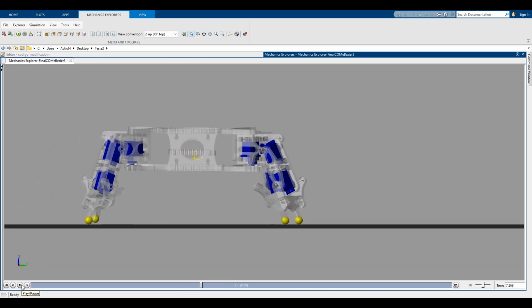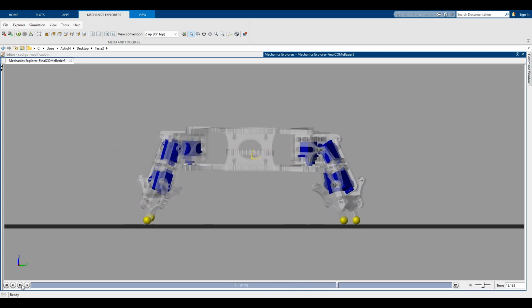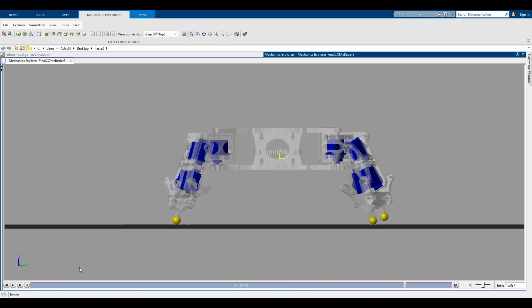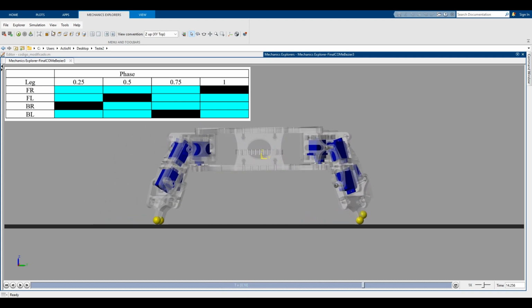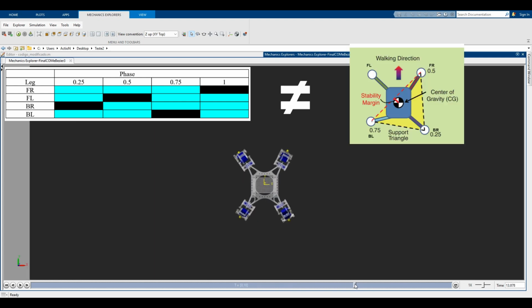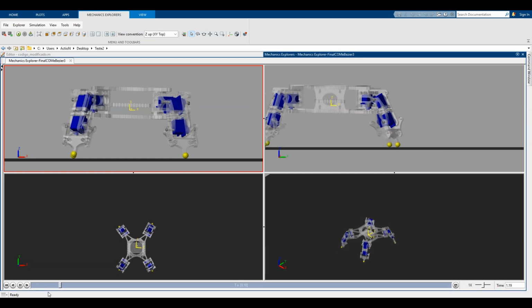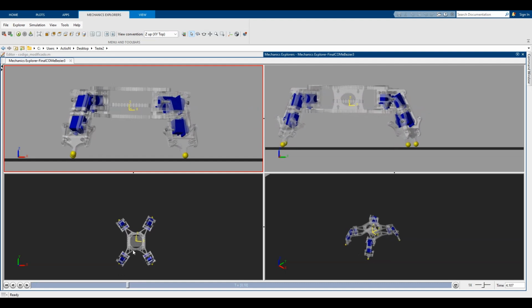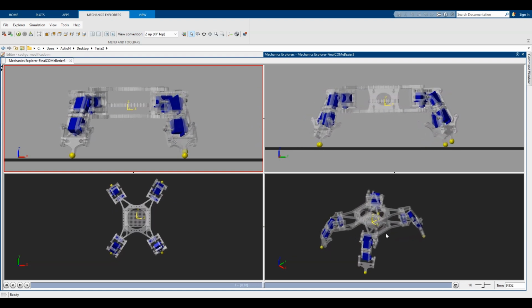In this section, we present the simulation of the quadruped robot executing a crawl gait. As previously described, the gait uses a diagonal leg activation sequence with phase offsets of 0, 0.50, 0.25, and 0.75, corresponding to the order FR to BR to FL to BL. This variation from the standard gait presented in the reference paper was intentionally selected to demonstrate the flexibility of the trajectory generation framework. Throughout the 18-second simulation, the joint angles calculated by the inverse kinematics are continuously applied to the robot model, allowing it to execute 3 complete walking cycles.